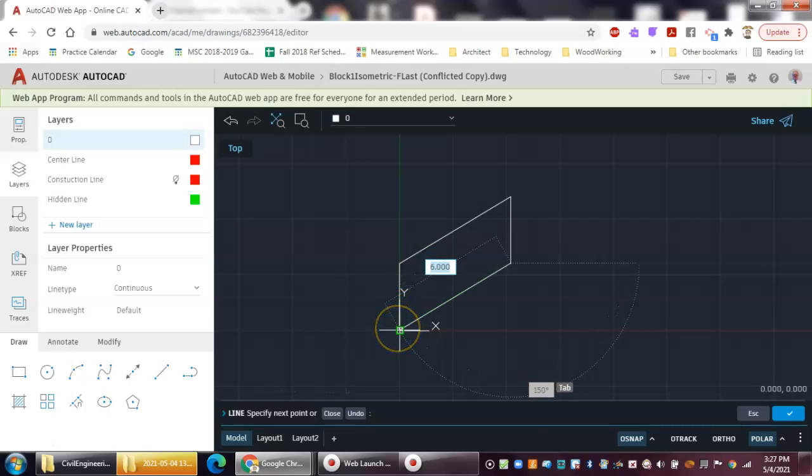Now I connect that parallelogram. Notice it clicks in. I'm at 6 inches and 150 degrees, which makes sense. I'll left click to enter. Now I'm not done drawing, so I can go up and to the right, and lock that in at 30. Again, notice in this case we're at 150 degrees, and this is going to be 1.5 on my depth.